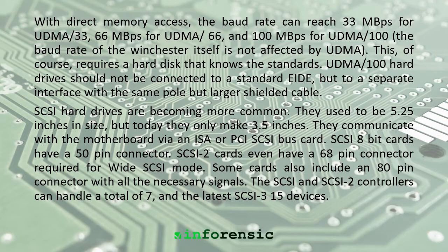SCSI hard drives are becoming more common. They used to be 5.25 inches in size, but today they only make 3.5 inches. They communicate with the motherboard via an ISA or PCI SCSI bus card. SCSI 8-bit cards have a 50-pin connector. Some cards also include an 80-pin connector with all the necessary signals. The SCSI and SCSI 2 controllers can handle a total of 7, and the latest SCSI